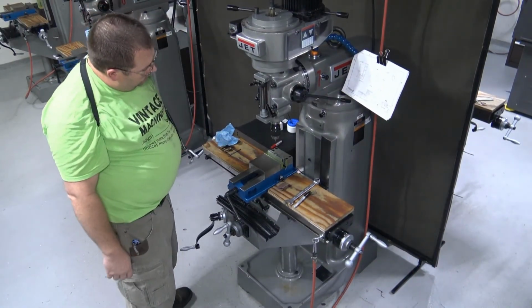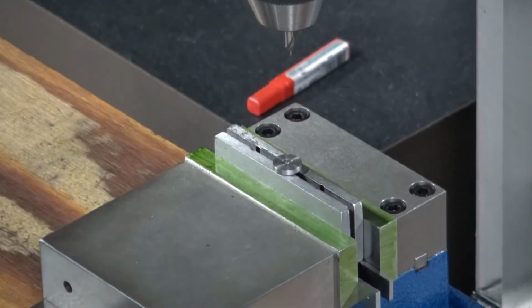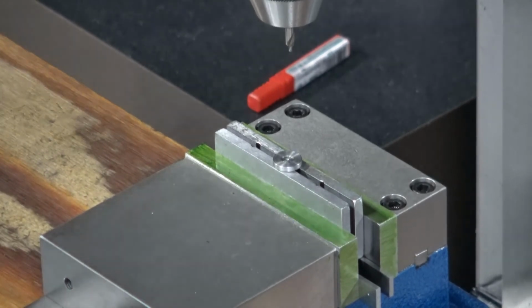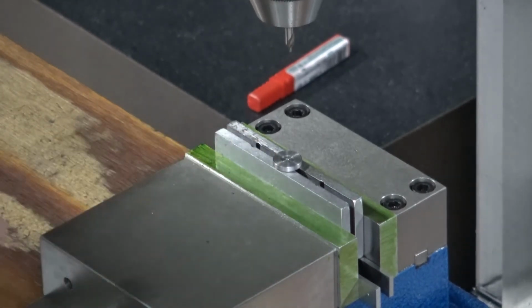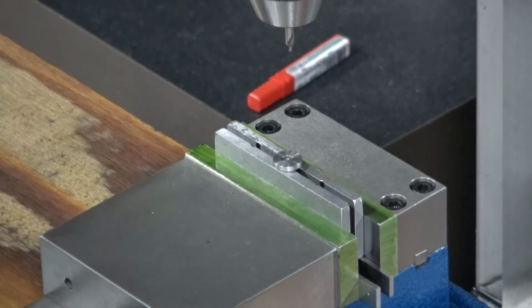Okay, so now I have put my center drill in. I've already gotten into position, okay? We're going to put so little cutting force on the workpiece that I'm not worried about the table moving around. But if you'd like, you can just kind of lightly tighten up on that x-axis. The y-axis, if I were to bump that hand wheel, I'm going to need to go back and re-indicate that